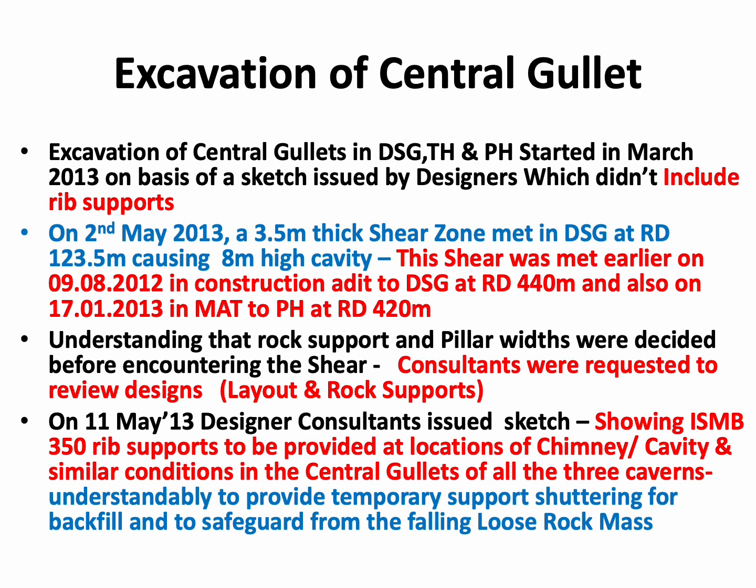Understanding that the rock supports and the pillar widths were decided before encountering the shear, consultants were requested to review designs. The project authorities requested the Central Water Commission, the consultants, to review the designs of layout and rock supports in light of these findings that a shear zone has been met in construction adit to the Downstream Surge Gallery and in the main access tunnel to powerhouse, which by the studies of the resident geologist may also intersect the three caverns.